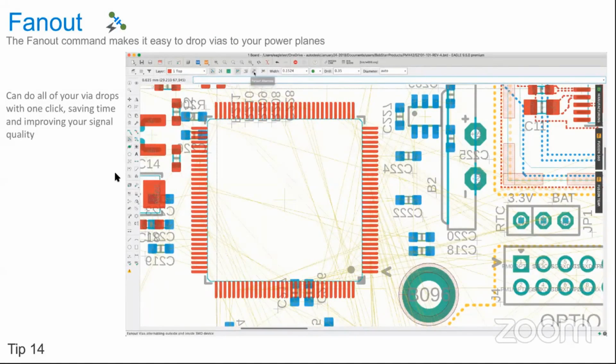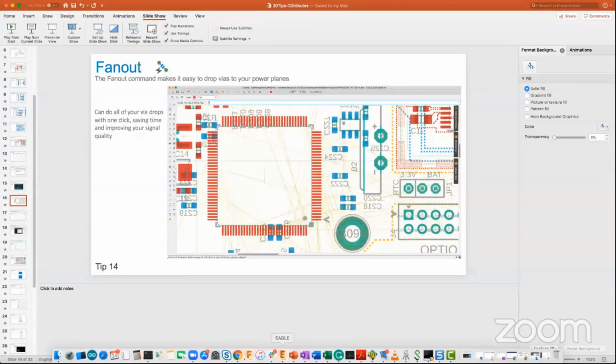Another question that we have is about the miter function. Basically, what the miter function does is that it takes any corner and it chamfers it. Either chamfers it in a curve angle or it chamfers it in a 45-degree style angle. Yeah, if anybody uses Fusion, miter is basically fillet. The same command in the Fusion sketch space is basically a fillet.